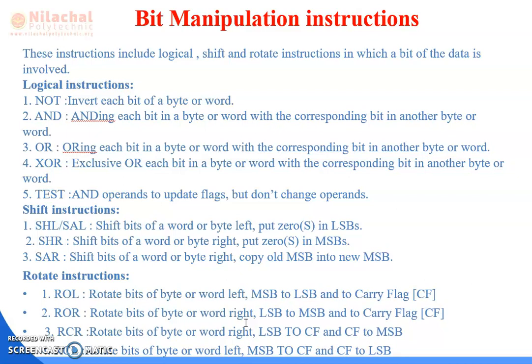Next OR means ORing each bit in a byte or word with the corresponding bit in another byte or word. Next XOR means exclusive OR each bit in a byte or word with the corresponding bit in another byte or word. Next TEST, that means AND operation to update flags but don't change operands.